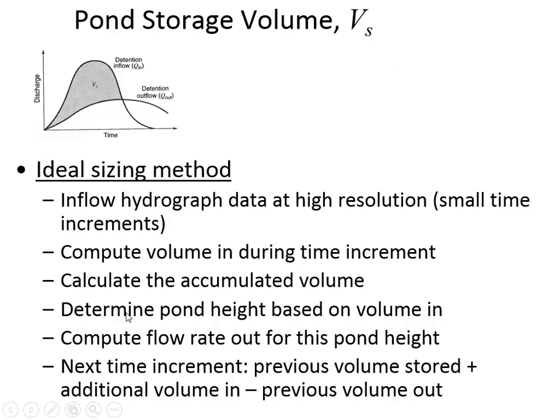And then we'll find out how much volume there is, what's the pond height. And then if you know the pond height at that increment, then you can say what the flow out is. And you're going to use the flow out in the next hour when you move the row down.